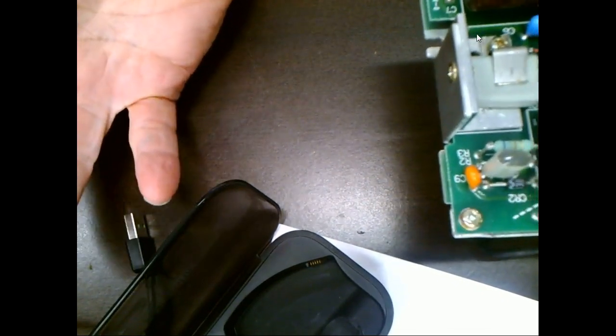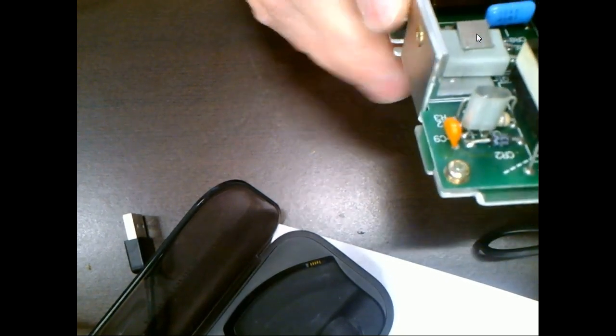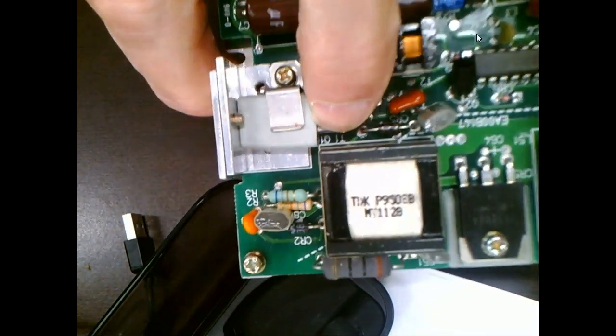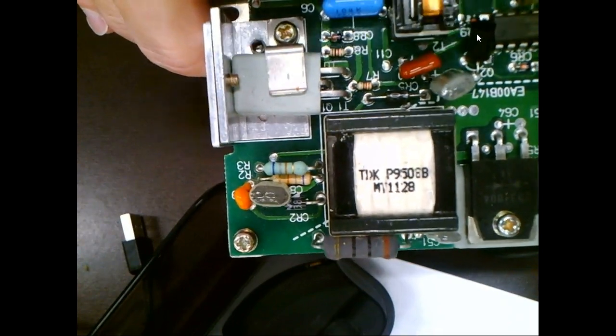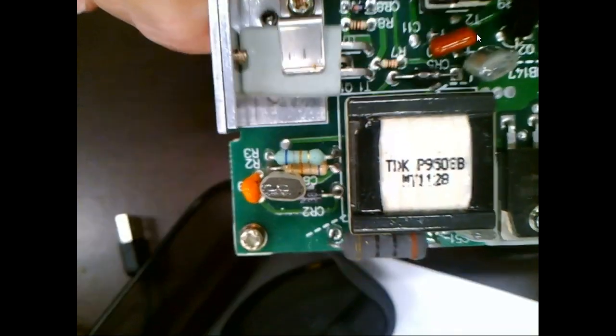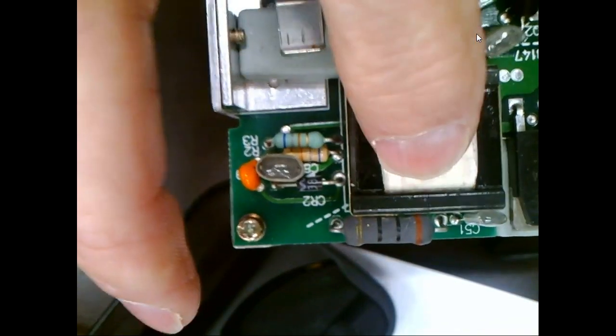Well, I know it's got 3 leads, but the solid state components that could be would be quite a few, as long as it fits in that package, right? You understand? So if I see a Q, and there's a T1 right there beside the Q1, if I can get this, can y'all see the T1 and the Q1? Well, T1 means this right here is a what? A transformer. It's not an inductor.